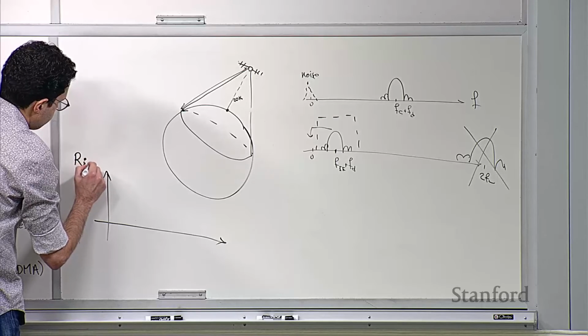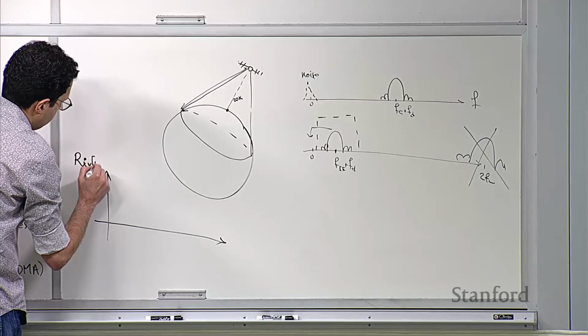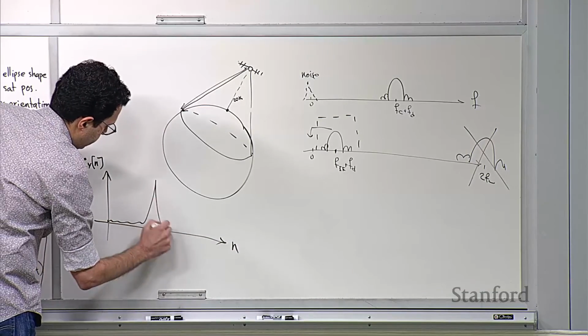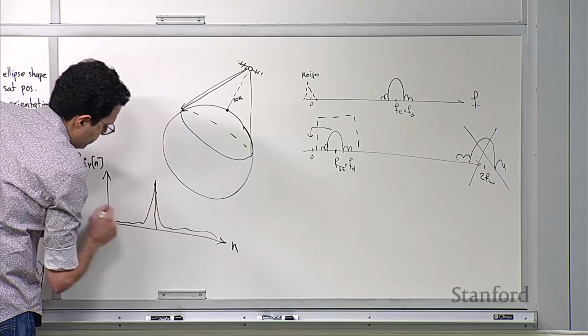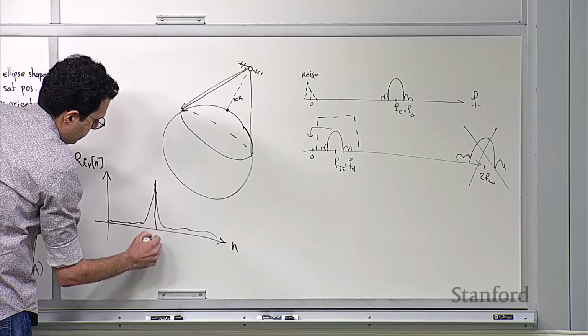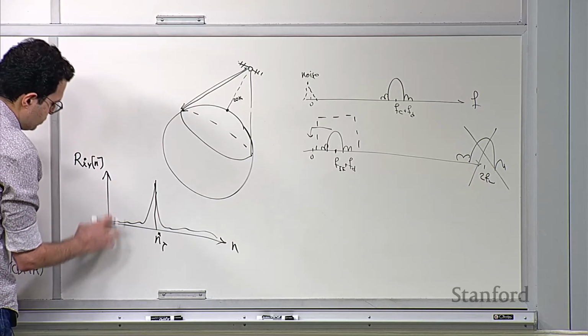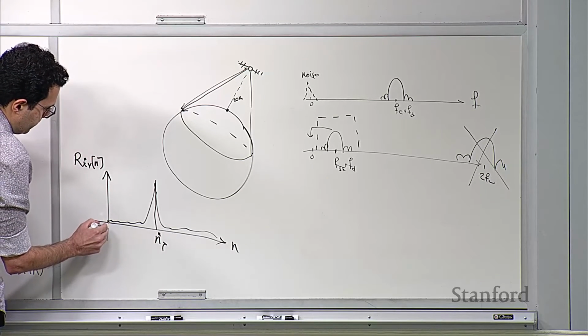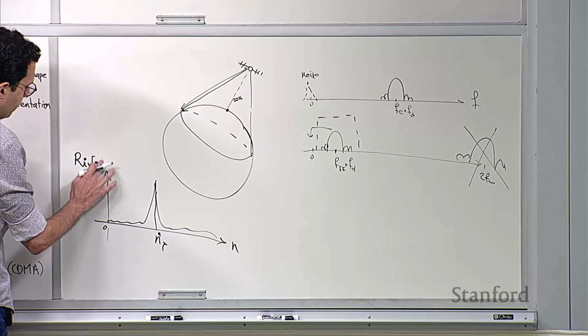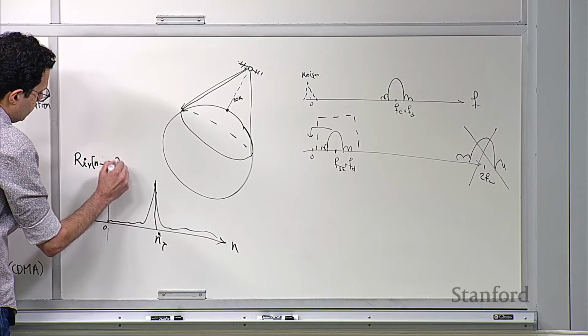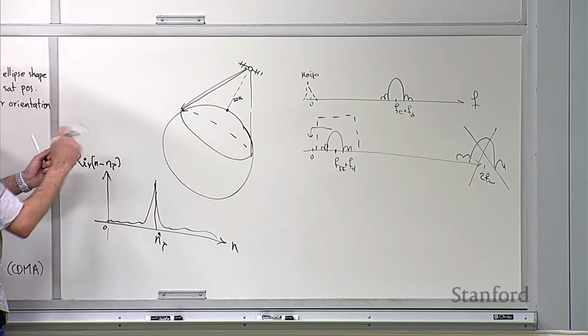So instead of calculating r x hat y of n as a function of n, and then searching through this function and finding where our n hat tau is, which is one way of doing it, the receiver actually just monitors the output of the correlator at 0 and varies the n tau as a knob.